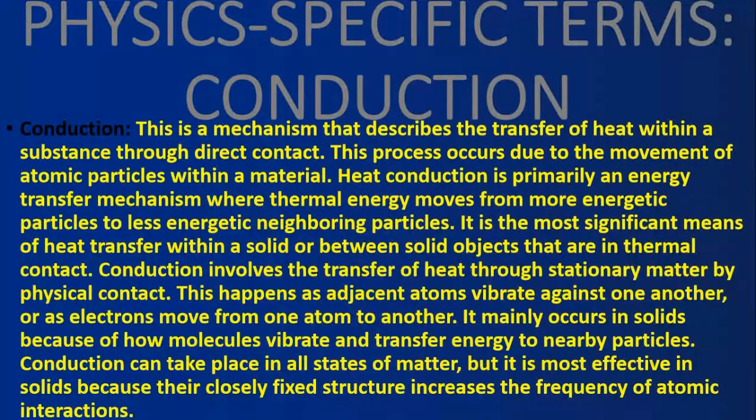Conduction involves the transfer of heat through stationary matter by physical contact. This happens as adjacent atoms vibrate against one another or as electrons move from one atom to another. It mainly occurs in solids because of how molecules vibrate and transfer energy to nearby particles. Conduction can take place in all states of matter, but it is most effective in solids because their closely fixed structure increases the frequency of atomic interactions.